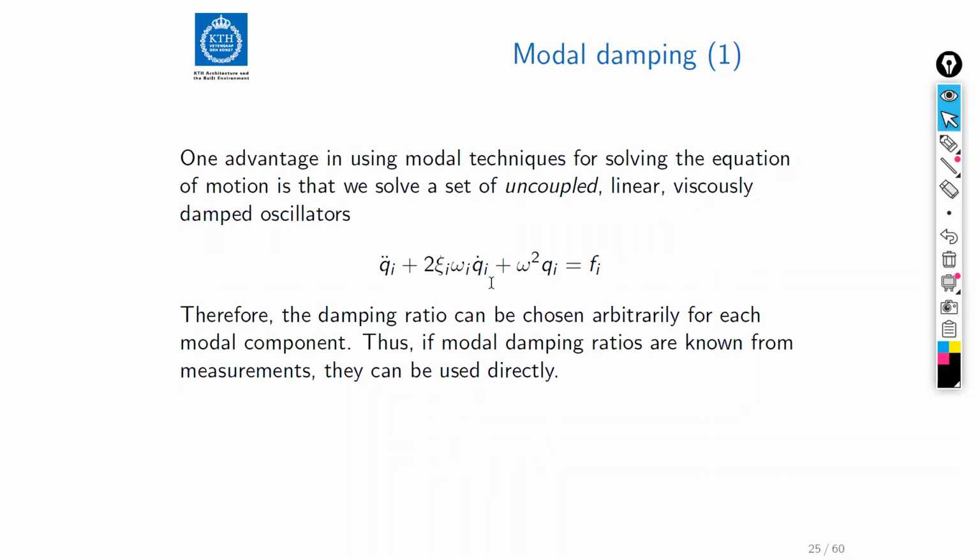And if we start considering trying to do actual engineering judgments based on these theories, we will find in the standards related to dynamic analysis, in Eurocode, in old Swedish standards, and in other international standards, recommended values for the modal damping ratios for different materials.